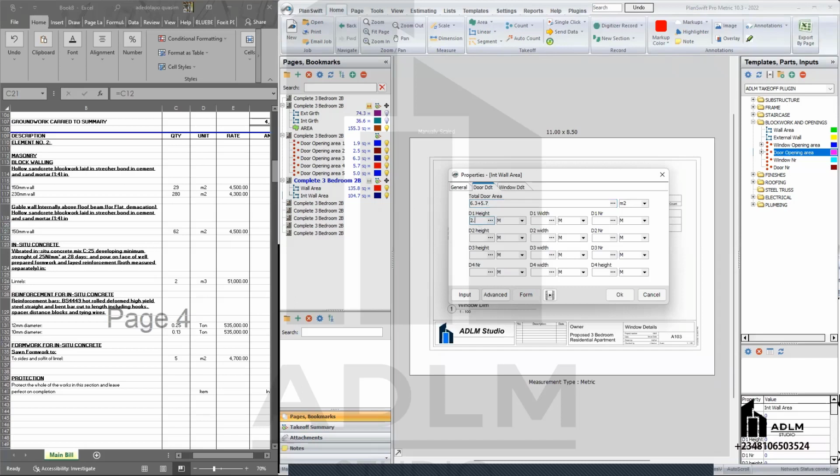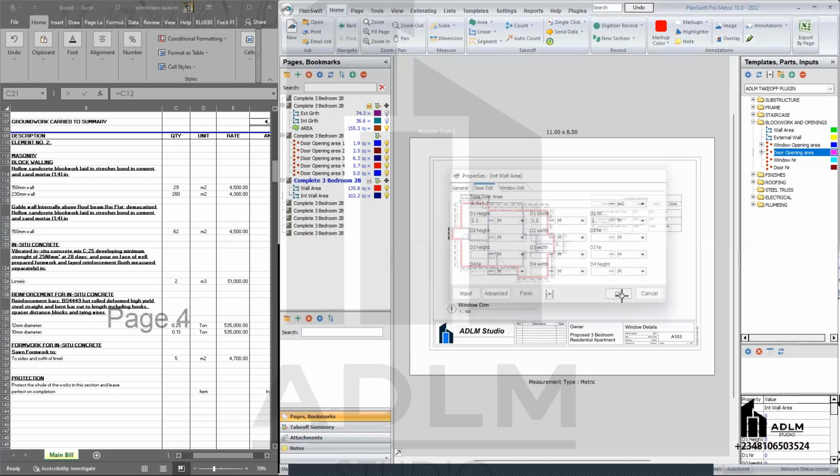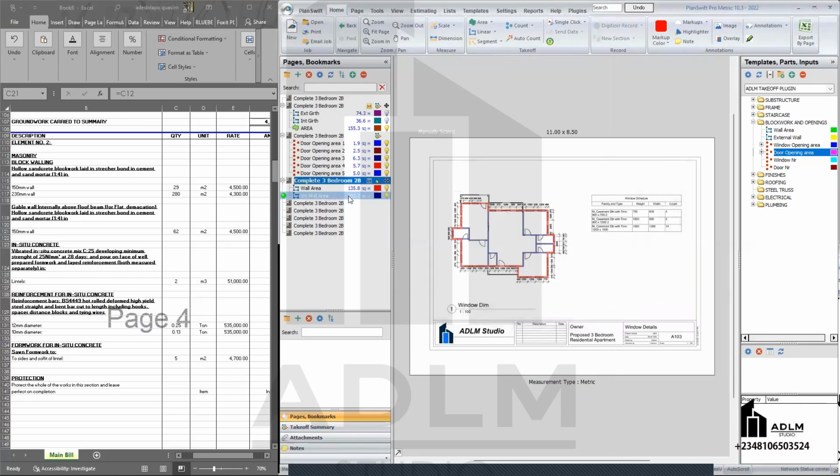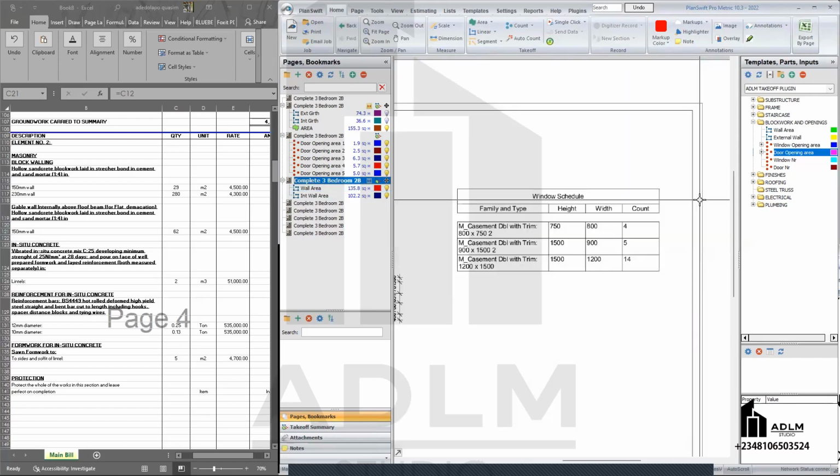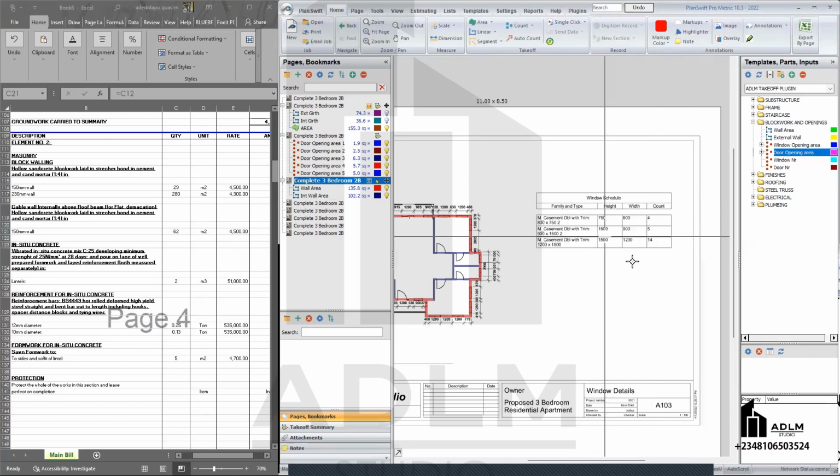You choose to do it that way, or just put the dimension. That's 2.1 by 1.2 by 1. Still the same thing. Okay. Now you see that's reduced. So this is your exact wall area, and for this also. Now some of you will be like, oh, what of Lintels and the others? We'll get to that now. Hold on. Now for this also, you have to pick the Windows areas also that way.